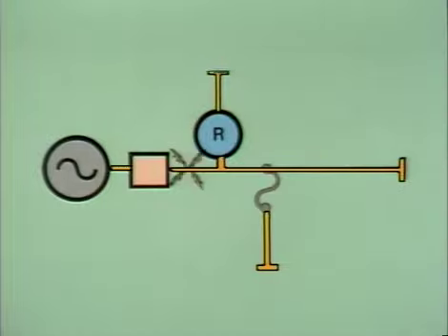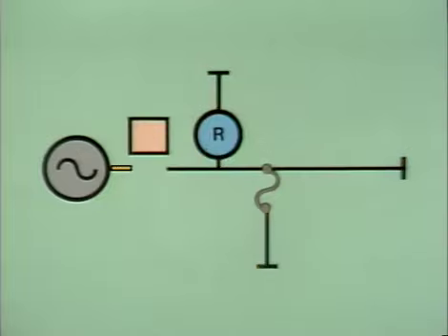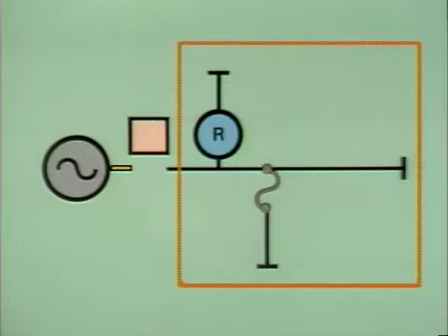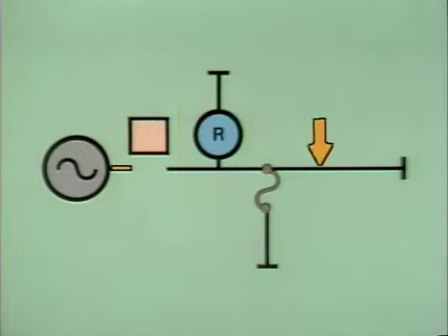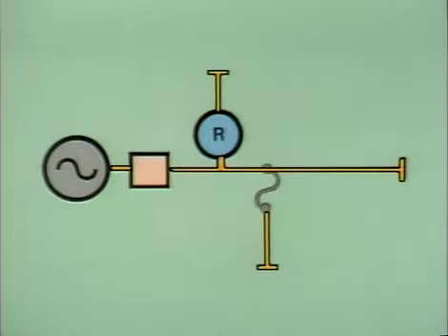Now, if the fault occurred here on the feeder line instead of the branch lines, the circuit breaker must protect the entire electrical circuit. When it detects a fault in the line, the circuit breaker switches open. This de-energizes not only the feeder line, but the branch lines as well. That's because the circuit breaker in this circuit is located between the power source and the rest of the electrical circuit. Now, in this case, the feeder line and both branch lines are protected from the fault. When the fault is cleared and the circuit breaker is closed, power delivery will resume.